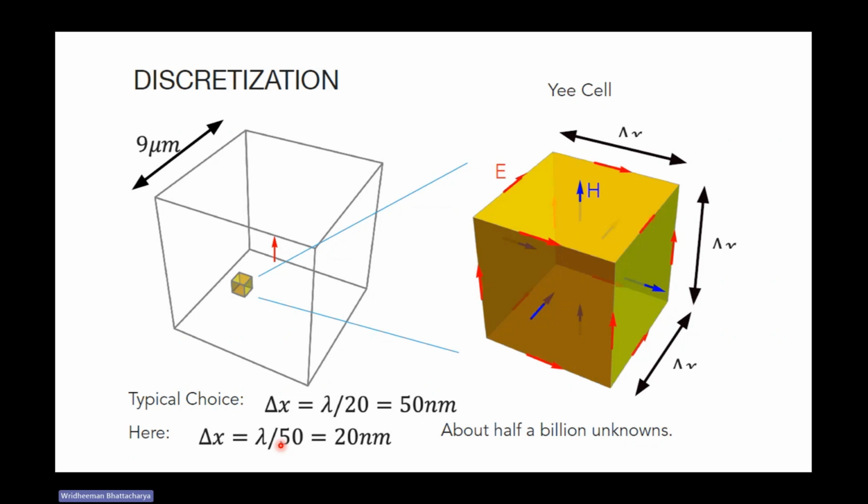Basically, what happens when we increase the denominator, such as 10, 20, 30, 40, is that at one point it saturates. So we have to find that saturation point so that our result does not change after that. Once we attain that saturation, we could say that our system is stable, and however we alter our devices, the result will change only upon the parameters which we are changing. Okay, so this is the main part of convergence testing, which we'll discuss.